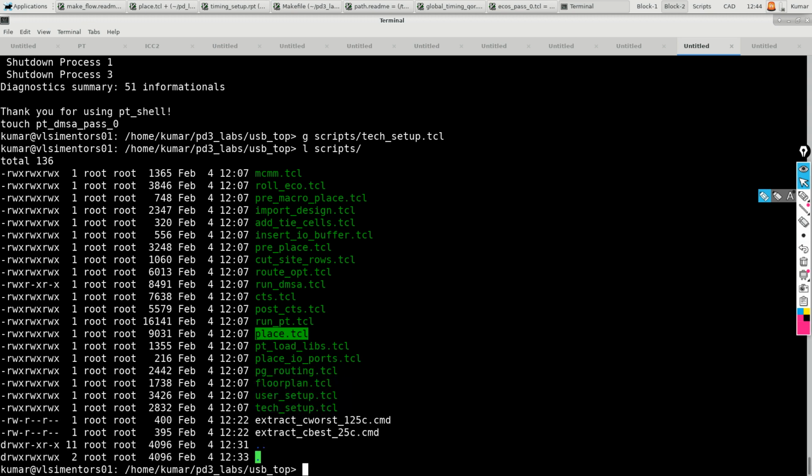Okay. Next, is there any thumb rule for floor plan and routing utilization? The starting standard cell utilization should be around 60. Anything higher, you might have trouble, and if you start too low, it might be a penalty for area. If you are working on CPU based designs, then it is a totally different ball game altogether, because CPUs would always be targeting 80% or 85% end utilization. So it all depends.